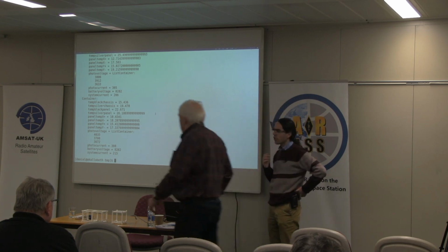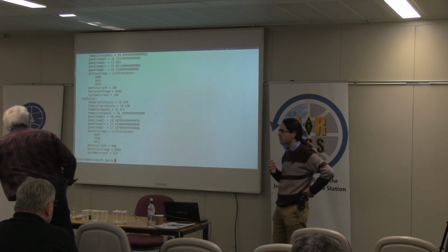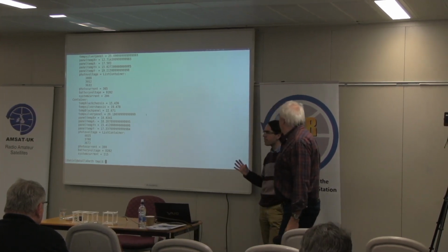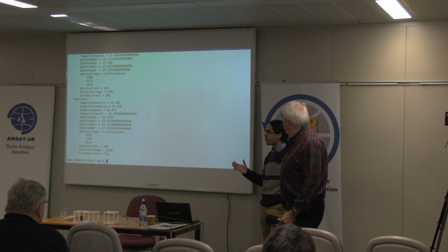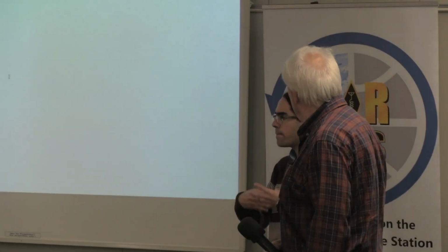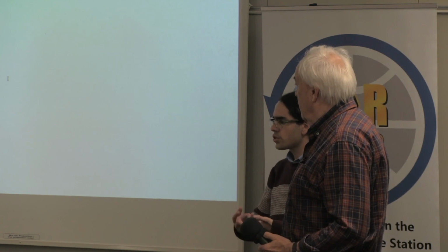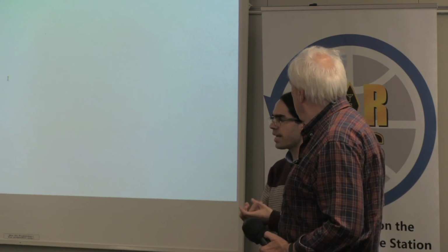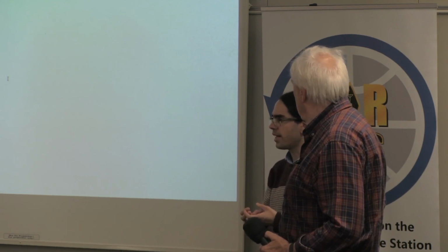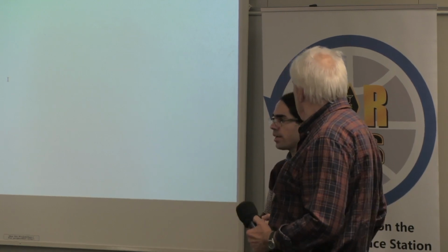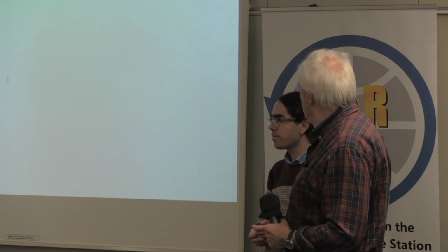Yeah, I'm not sure. That's a very good question, because on QO100, one of the things you have is the phase noise or frequency stability, if you wish, of the downlink of your LNB, because many people don't have a GPS locked receiver. So you need to design a waveform which is able to cope with that, and this 8PSK manages to do so in a really good way.